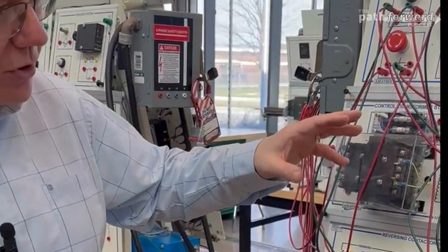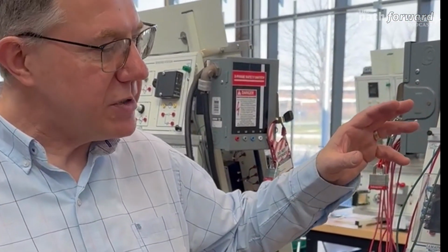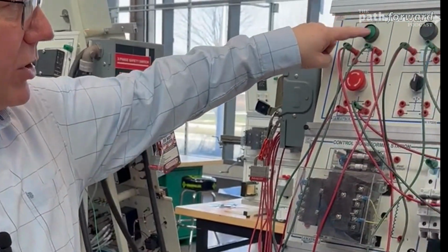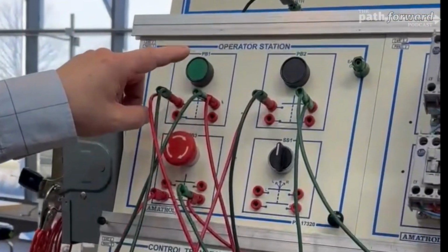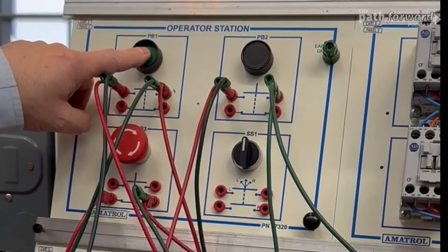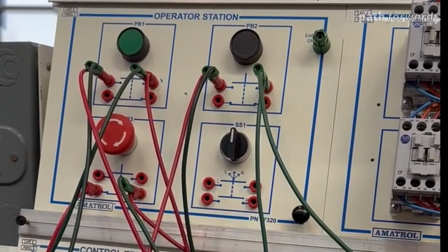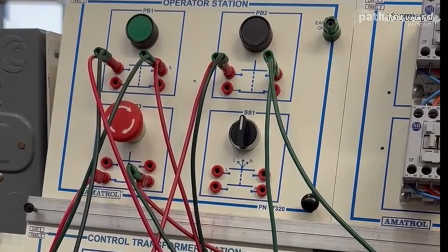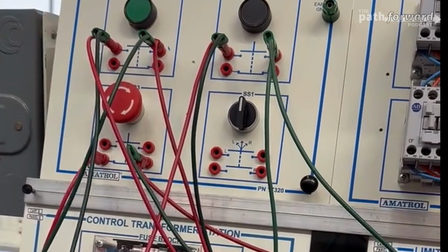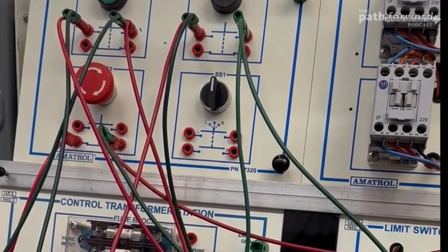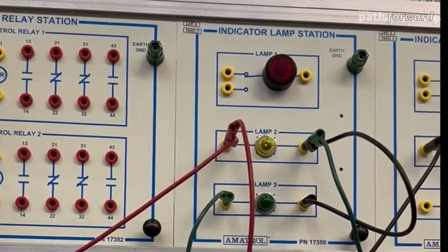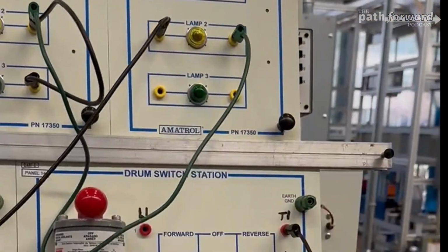You're wiring up the circuits and learning how to troubleshoot those circuits. Just as an example, when you press a start button, if it's not wired up correctly, you can press the start button and the motor or whatever you're starting might turn, but when you take your finger off the button, the motor might stop. You have to have what's called a latching circuit, so it's a special wiring of the different components and special contactors that are involved in that, and that's what you'll learn about in this class.